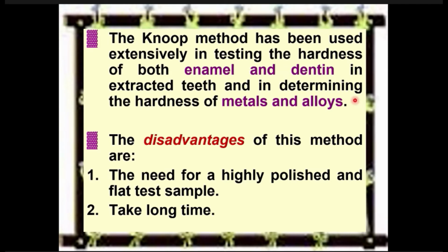Okay, so what is the disadvantage of this method? Because the indenter is a very fine shape, we cannot test a material that has a rough surface. We need a highly polished surface, and it may take a long time because we need proper sample preparation for this method.